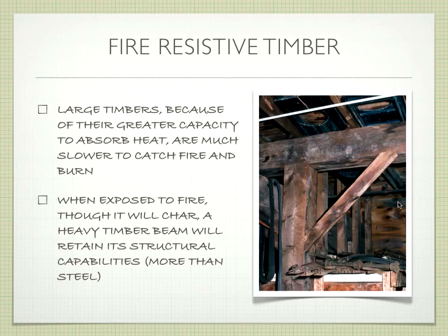It's going to happen, but it's much harder. And if you have a similar sized beam, steel's going to fail faster if it's exposed to fire than a heavy timber. So you would think, wait, wood burns? But it has to do with the size and the amount of material that you're working with. So it ends up being a very fire-resistant material.